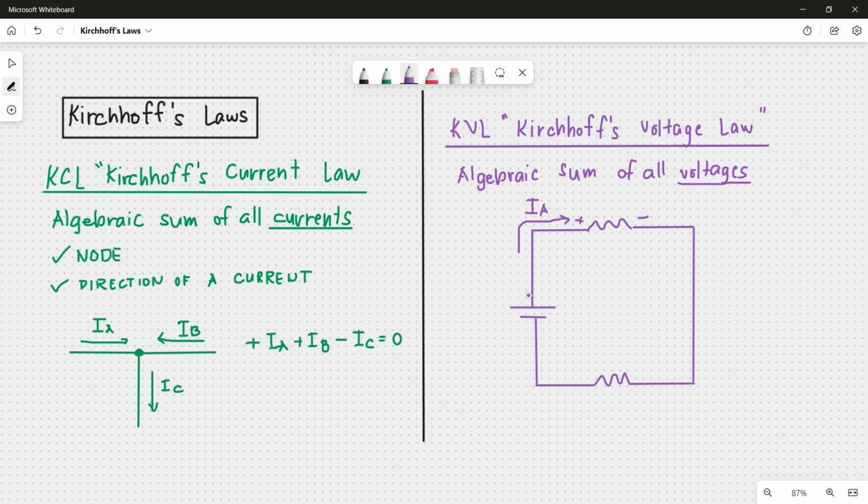So if, for example, we saw that this volt source has a positive sign here, we know by default that the current is flowing in this direction. And even if this element does not indicate the positive or negative polarities, we must already know that this side is positive because current enters here and leaves on the other side, which makes this a negative.